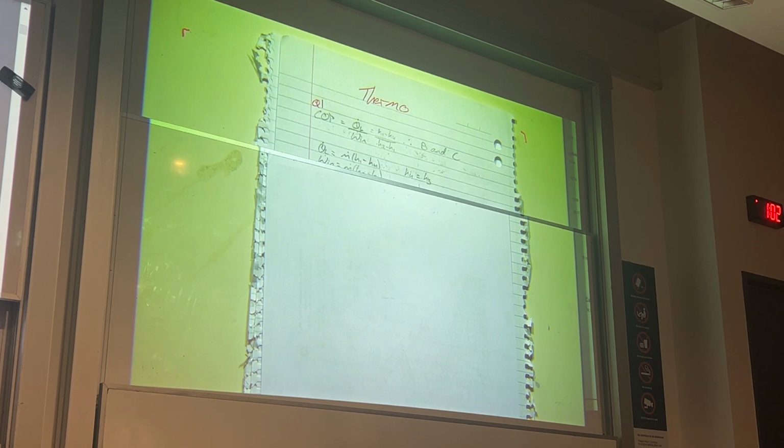And you can see H1, state 1, is always at the same point, so this doesn't change. However, when we go to state 2, we actually draw state 2 down. So our network supply decreases, and then our heat rejected decreases as well, because our state 2 comes down to here. So that's a pretty simple one. Hopefully you can get both of those.